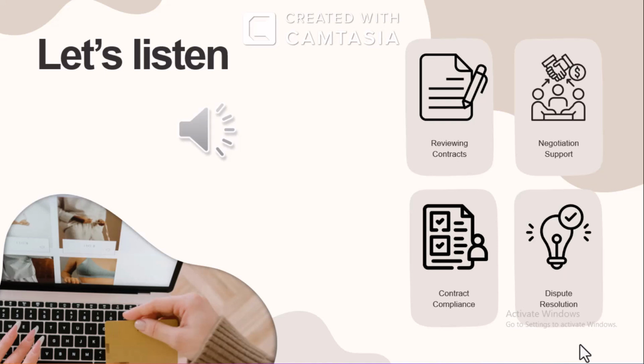Good job. But let's check if the machine picks up components properly now. Oh, the pick and place head keeps missing components. That could be a nozzle clog. Did you inspect the nozzle hole? No. Let me check. Oh, there's some dust inside. A clogged nozzle reduces suction power. Try cleaning it with compressed air. Okay, done. Let's test again. Yes, now it's picking up components properly.